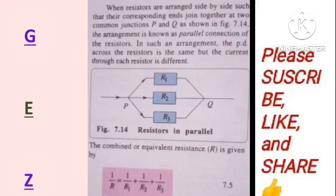On the other hand, there's another configuration which we could use. That is known as the parallel configuration, and that is what is being shown in this diagram in this video. This arrangement is characterized by the fact that the potential difference across the resistors is the same, but the current through each resistor is different. So if you test R1, the potential difference of R1 will be the same, the potential difference of R2 will be the same, the potential difference of R3 will be the same. This is because they are in the same state, so they have the same potential difference, but their current is different.